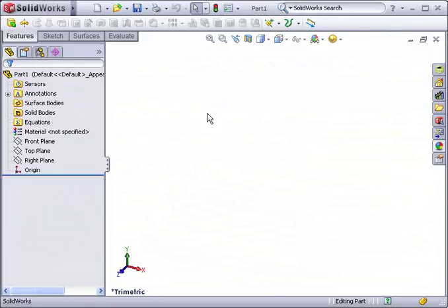While you can't mate polygonal shapes concentrically in SOLIDWORKS, you can use other geometry associated with the polygon to create the references you need to properly create the concentric mate. There are a few ways to do this. One way to quickly get the references you need is by using the Polygon Sketch tool.